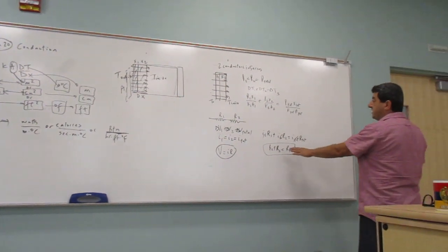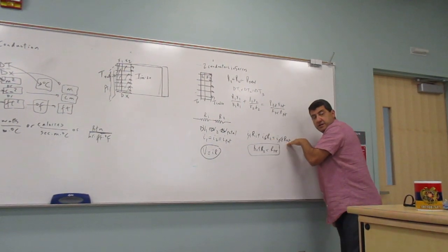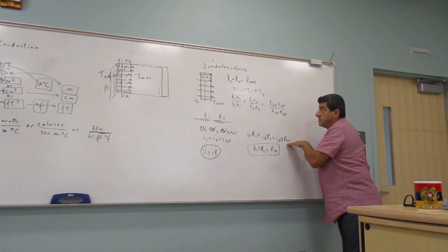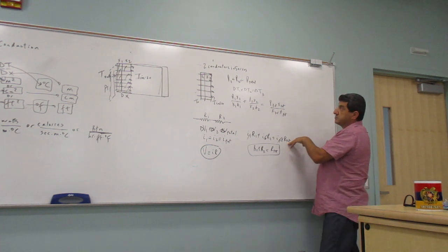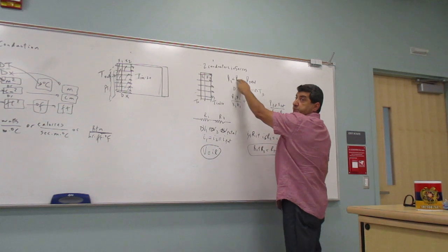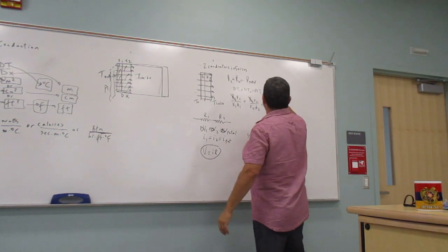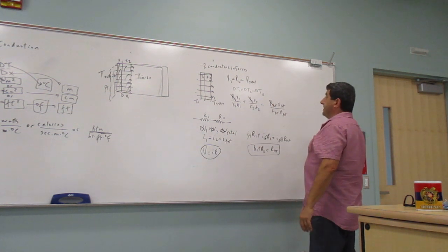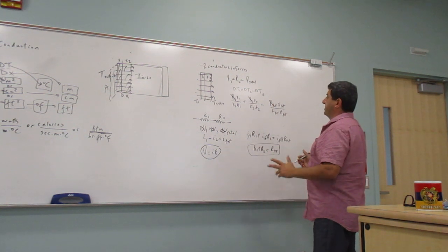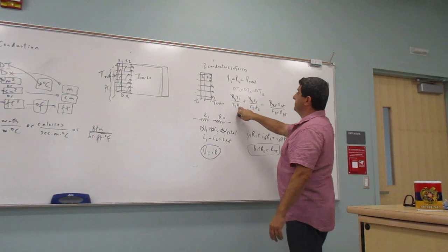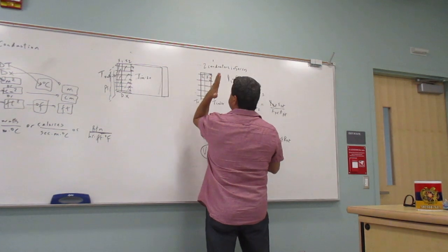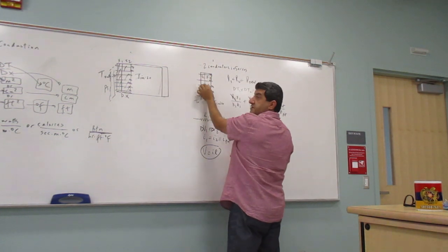Then we look to see if we can cancel some stuff. So first thing we can cancel is P1, P2, P total, since in series they're the same. This one, this one, this one cancels. And we might also have other stuff that are the same. So A1 is the surface area of this. Remember, it's not this surface area that you're looking at.